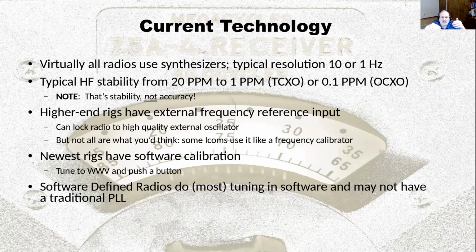Software-defined radios, which are the latest radio technology, do most of their tuning in software and may not have a traditional PLL, but the same kind of concepts apply. Now, it's important here to mention that 20 parts per million down to 0.1 part per million, that's talking about stability and not accuracy.